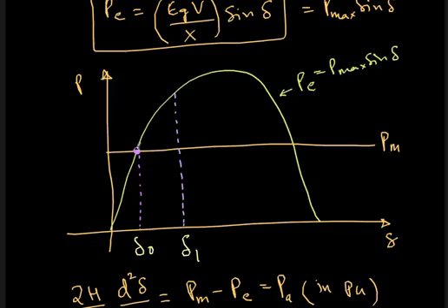At this point PM equal to P, but after this electrical power is your x-axis and mechanical power input is y-axis. So this much of variation is there. This much of power is being submitted to the rotor. Therefore this area A1 is proportional to the total energy.